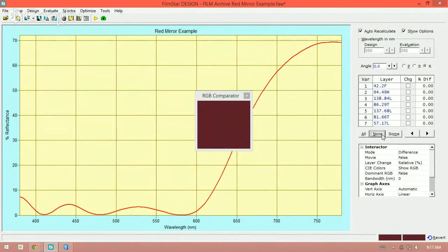And if I think there's a problem, I do some assessment. If the coating doesn't come out quite right, the color doesn't come out quite right, I look at all the variables, the materials, the deposition rates, oxygen input, and so on and so forth. And if I think I see a problem with a particular material, or a particular layer, I can take all the high layers.